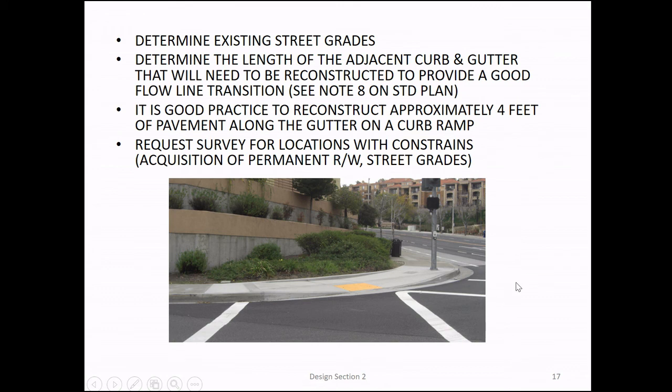Okay. Jose, I have a question. Yes. On the previous one, where you said we could angle the curb ramp to avoid stuff, how much can you modify that before you're reaching? Oh, not much, because you'd have sight distance issues. I leave that up to you as an engineer. It's engineering judgment. You are licensed. But not much.